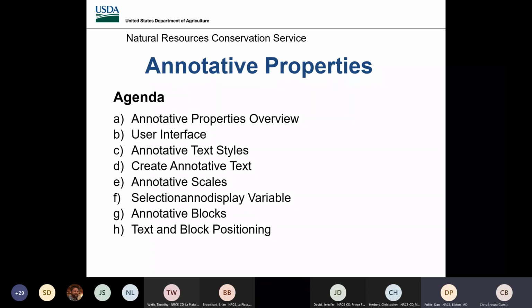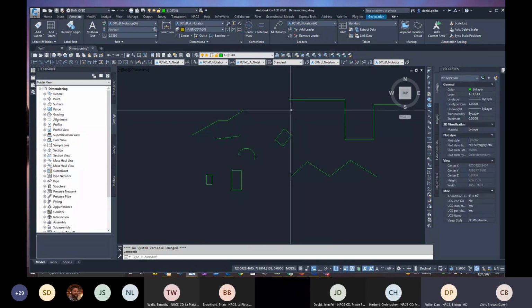Now, granted, if you want to make a text size a little bit bigger because you want to draw someone's attention, like a title or a subtitle, that's most certainly okay. But if you have multiple leaders going in the same area and they're all different sizes, something's not clicking right. So we just want to make sure all that is continuously the same throughout the entire drawing.